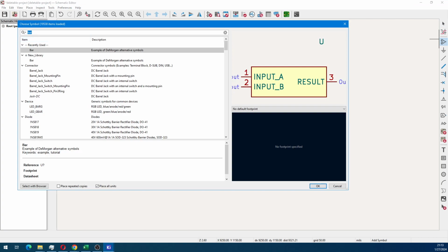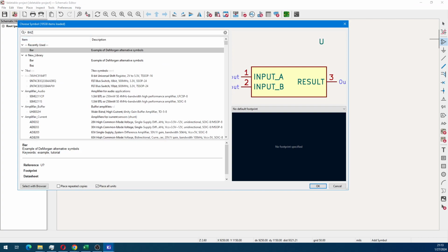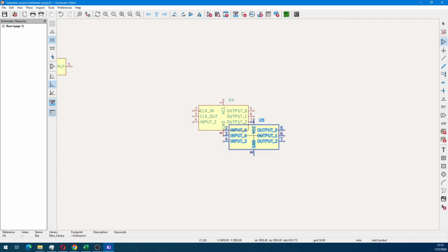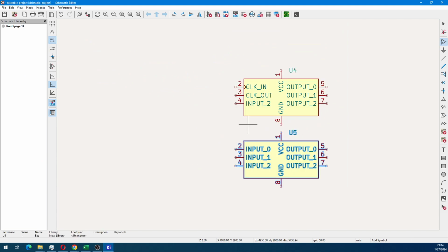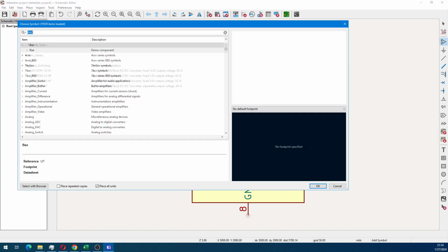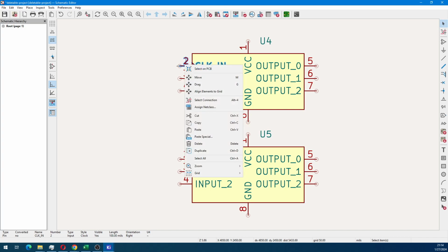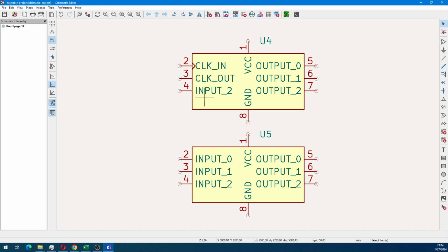So what I personally recommend is, if you're trying to do this, pull up the manufacturer's data sheet and use that, kind of like I did, to identify what the default pin functions are and what the alternatives are, because the defaults are usually what you get when the device first powers up and before your code starts running.